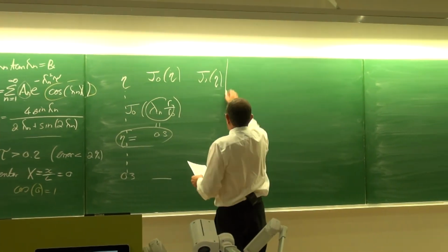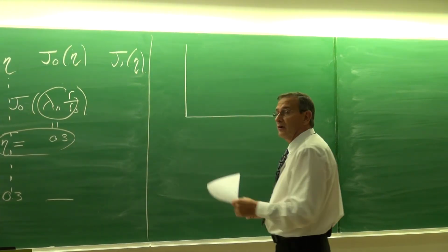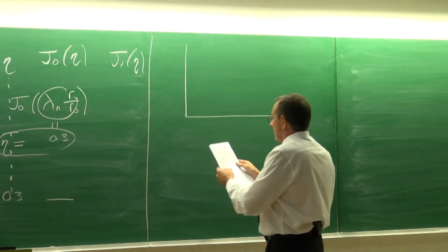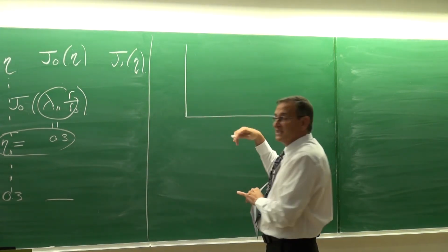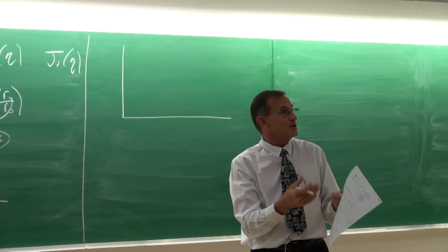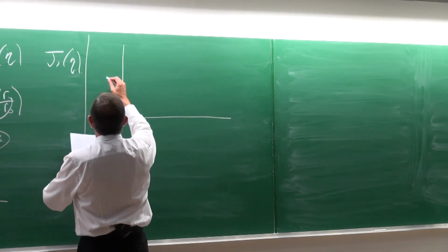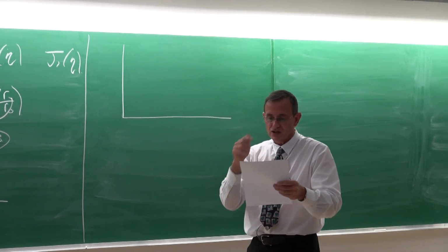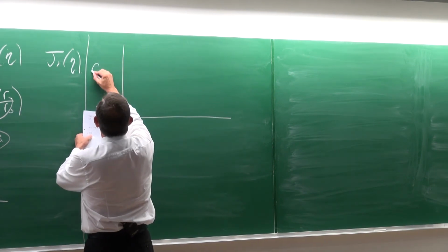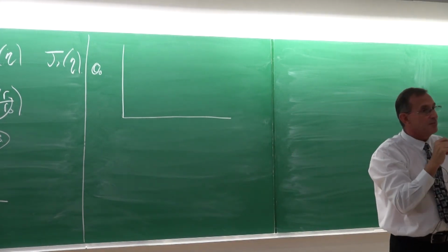The Heisler charts were developed by Heisler in 1947, and that was the time before computers, so it was a lot of work to do all these calculations. What he did is he presented the results in a graphical form so that it's easier and quicker, but of course it is not that accurate. How it works is, in principle, you will see that on every page there are 3 graphs. The first one is for theta 0. What does theta 0 mean? It is the temperature at the center.